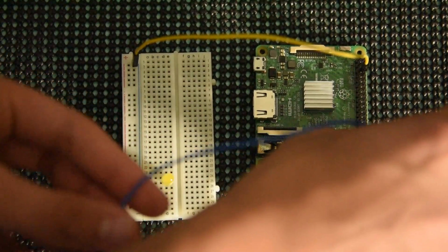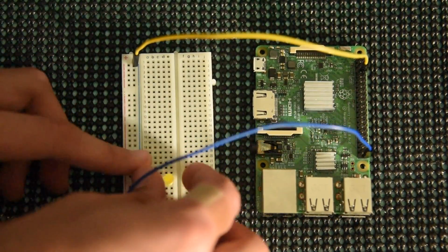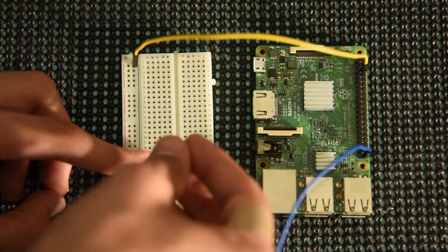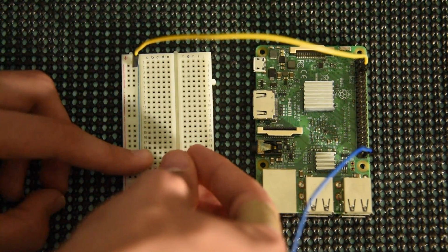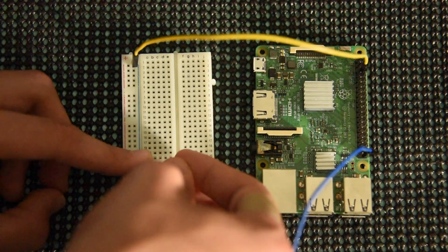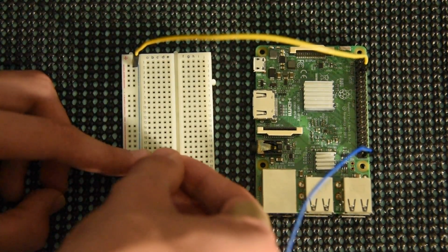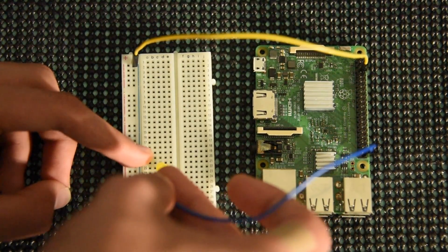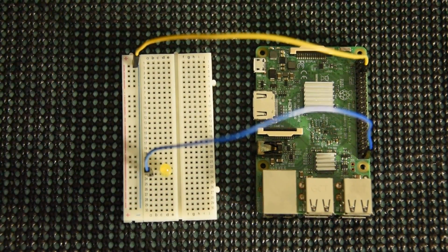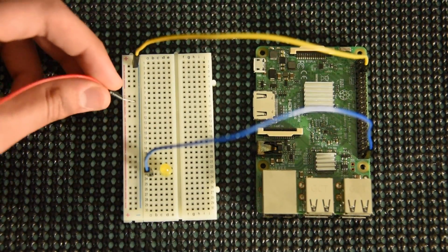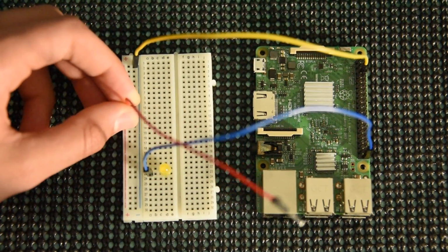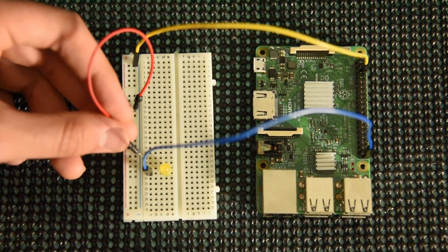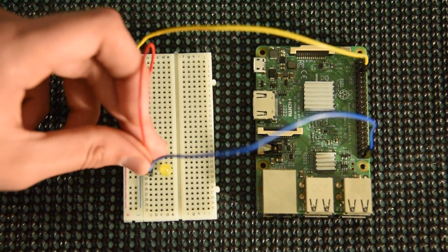After this, connect another wire from a random GPIO pin to the longer pin of the LED. This is where we can send voltage to the LED to turn it on. Some LEDs need a resistor, but since we have a yellow LED, that won't be necessary. Finally, using the bus we made before, connect a wire from the bus to the shorter wire of the LED. The circuit is now complete, and now we can begin programming it.